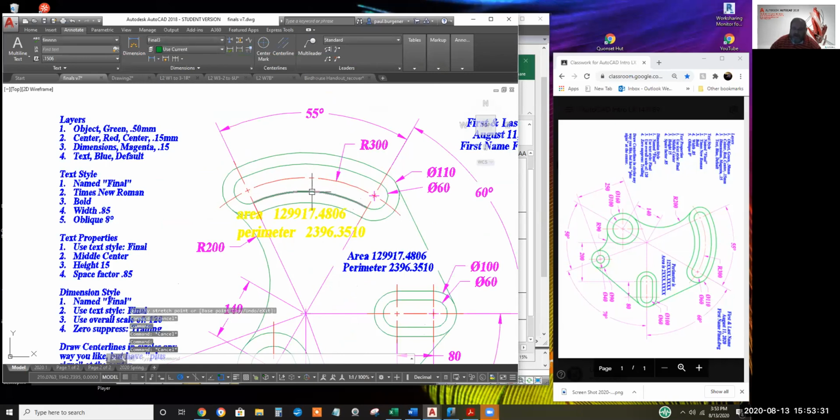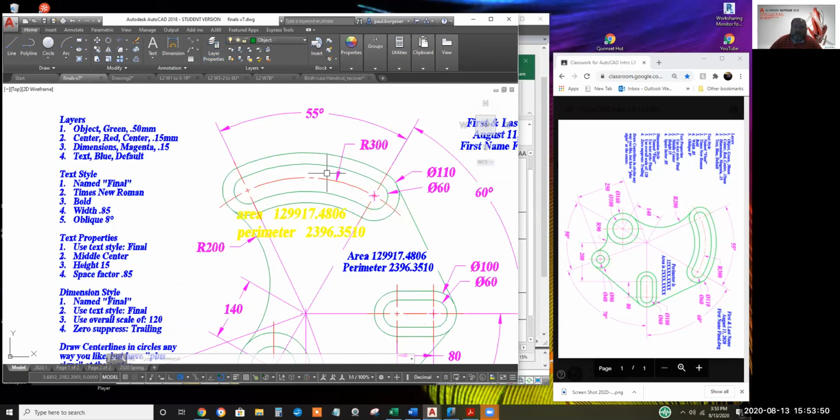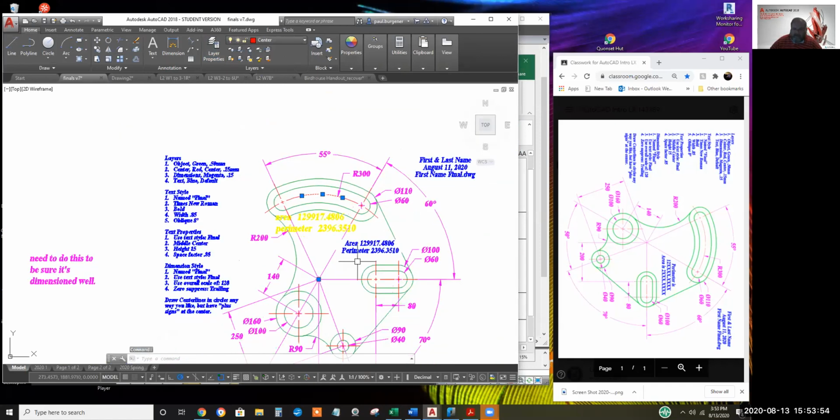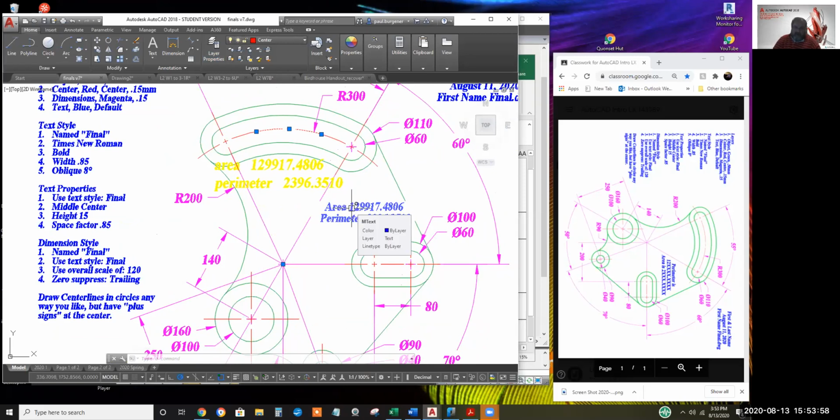So instead of my usual 3 layers of center lines, which I've been teaching for 20 some years, I just made a single layer of center lines, just one. And each and every arc or line has a specific linetype scale multiplier factor in its properties. Yep.